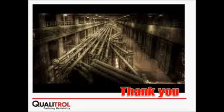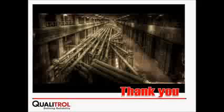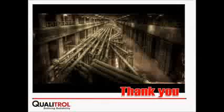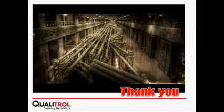Where would your locations be on the transformer? Basically just the bushing? No, it won't be in the bushing. If it's an existing transformer, it would be on the hatch cover, where you must do a retrofit in order to do localization. But you can also put an antenna in the drain valve without having to remove the oil, and at least capture the partial discharge there. We enforce that for new products: the new transformer should already come with the antennas.